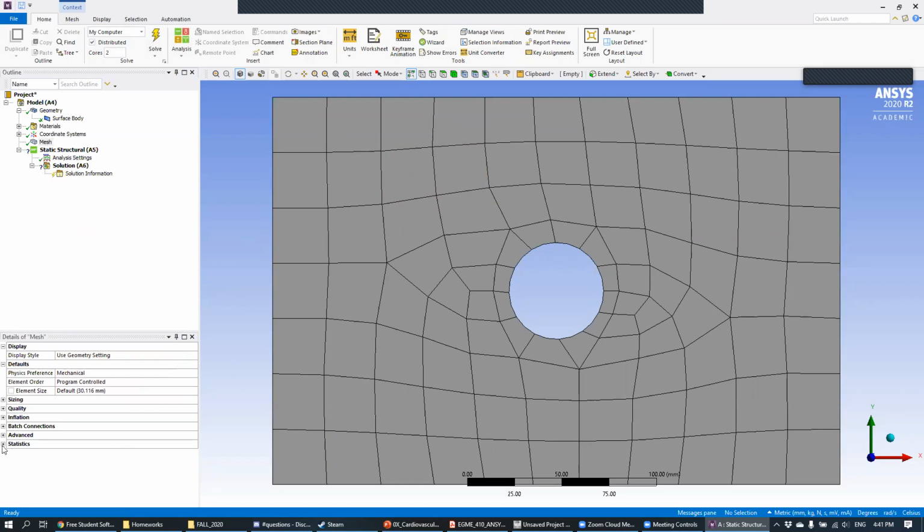So you can check how many shapes that you have and how many vertices that you have. Those are called elements and nodes. If you click this plus arrow next to statistics, you can see that this mesh has 351 nodes and 101 elements. You can count them if you want to verify it, but there's better uses for your time. So you can trust that the element count is correct. And this is the default mesh, if you want to just run a very quick simulation.